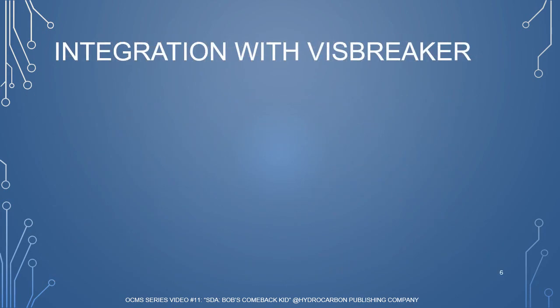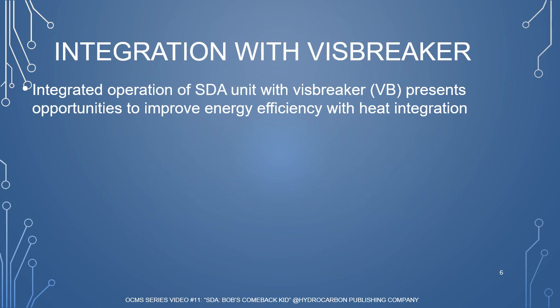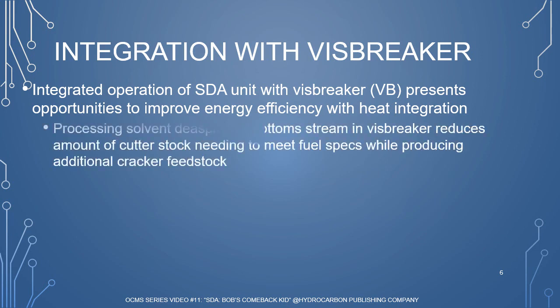The integrated operation of visbreaking with solvent deasphalting presents additional opportunities for refiners to improve energy efficiency with heat integration. The solvent deasphalter bottom stream can be processed in a visbreaker, reducing the amount of cutter stock needed to meet fuel oil specifications and producing additional cracker feedstock.